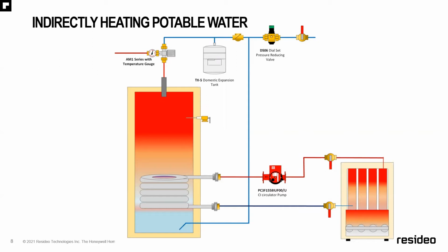That's because the design of that system is that it's storing hot water and maintaining that differential, which is plus or minus 10% on the top end. So it could have just ended its heat cycle at that point, and you were actually sitting on the higher temperature side because it overshoots to maintain that you're not short cycling the boiler. I said you put in a mixing valve and you can alleviate that issue.